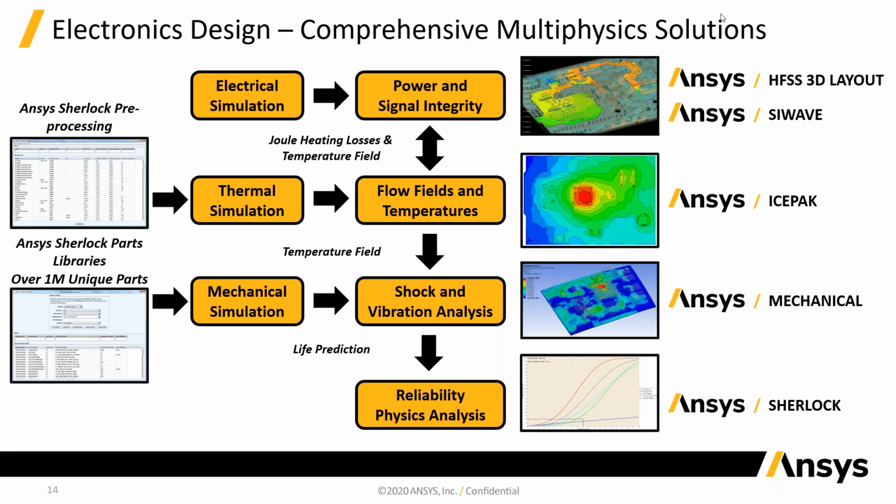So if you're looking to model a specific electronics component, there's a good chance that component's already in the Sherlock library, which definitely speeds up and makes it a lot easier on you when you're trying to set that simulation up. From there, in parallel, you will be running an electrical simulation using HFSS or a power and signal integrity simulation using SIwave.